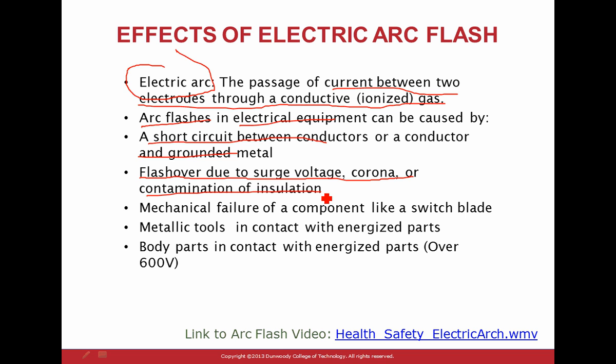Now you get into switch gear that's not insulated, and over time, if you don't do proper maintenance on these switch gear, guys, a 5-year or 3-year cycle maintenance where they shut them down, clean them, retorque them. If you don't do that, you have enough contamination that creates a path between a hot and a ground or a hot and a hot. At one time, you might open the panel, and at that moment, they arc. It escalates into a big ball of fire. So this is not a fault of your own. You're not doing anything here.